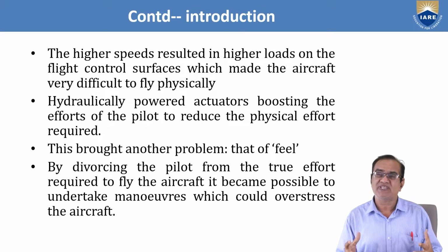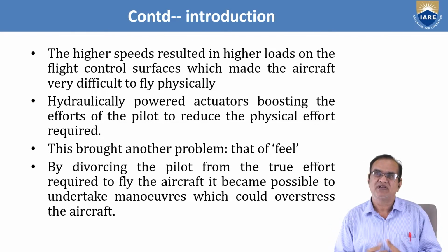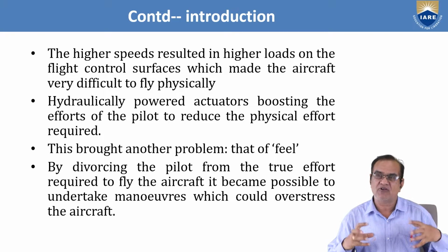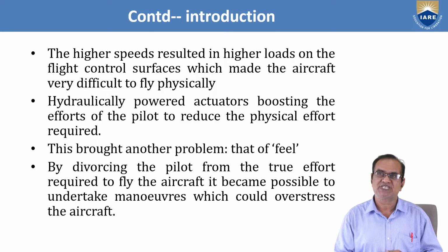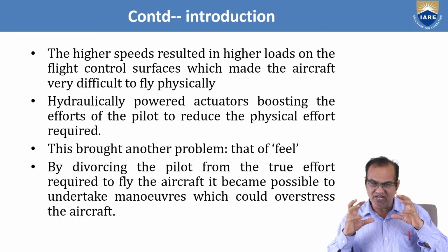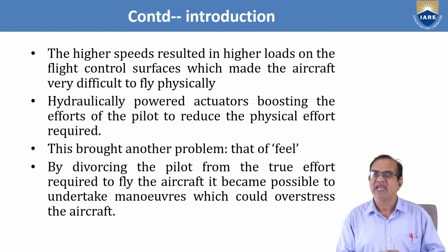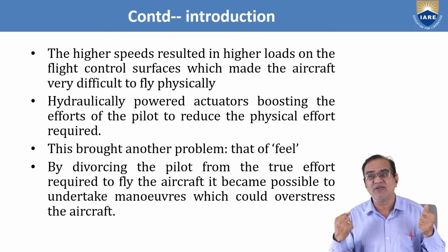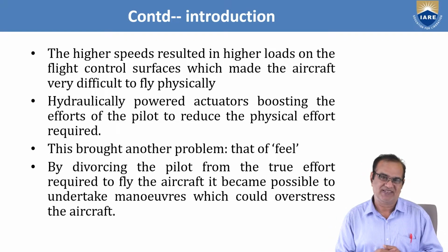So after that, they started the powered system. In that, hydraulic fluid was used, and it is hydraulically actuated boosters. So the pilot will give a little effort and it will be acted upon. This brought another problem, that of feel. In that, the pilot was not able to feel how much he is turning.